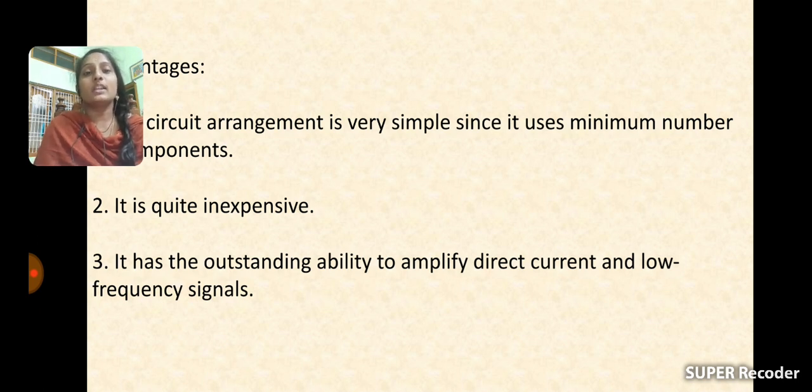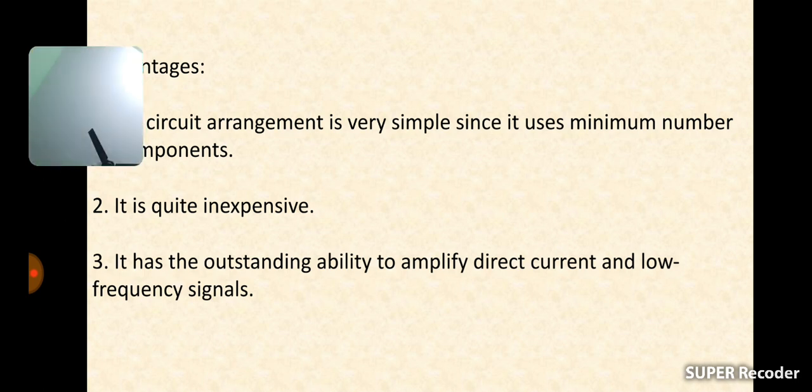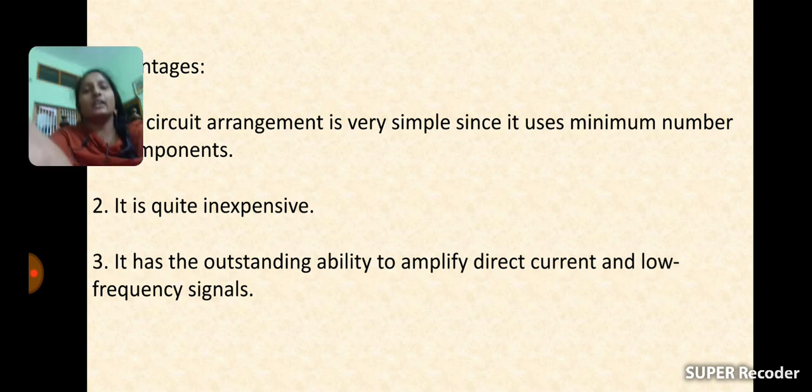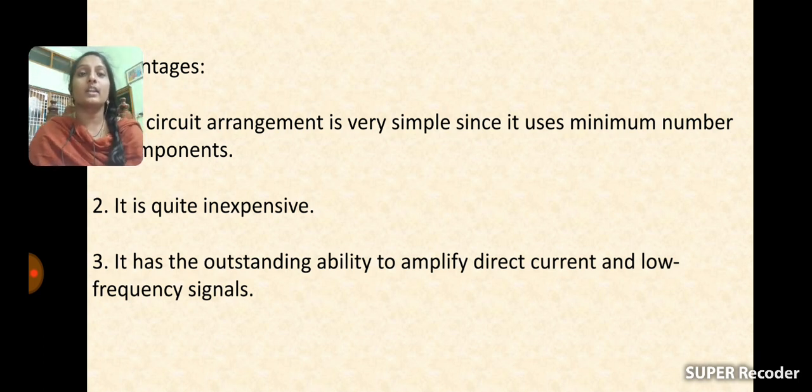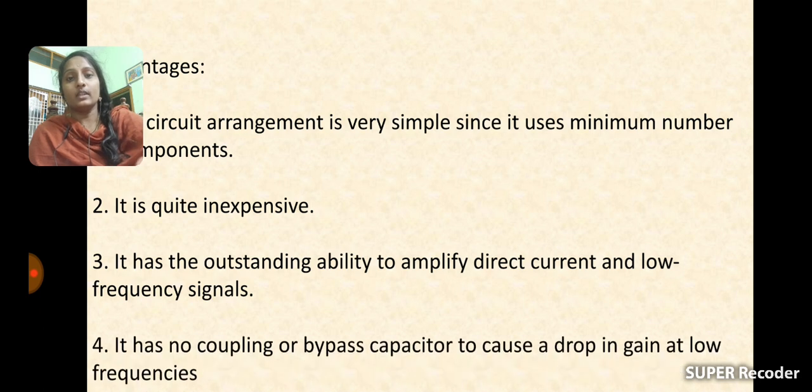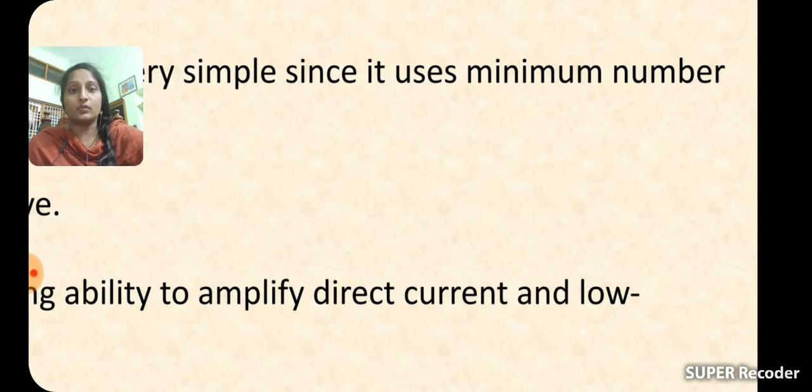It has the outstanding ability to amplify direct current and low frequency signals. This is the main feature of this amplifier. It also has no coupling or bypass capacitor to cause a drop in gain at low frequencies.